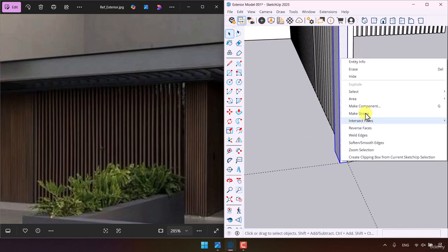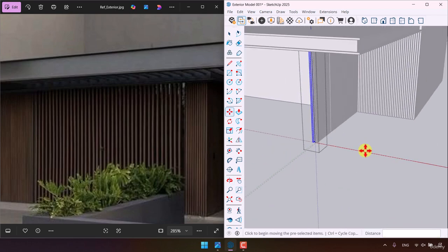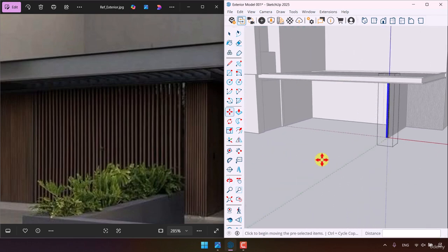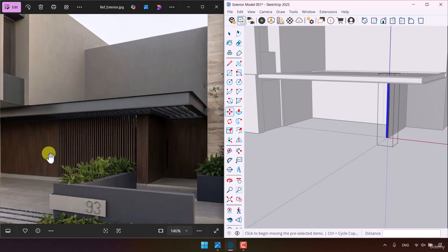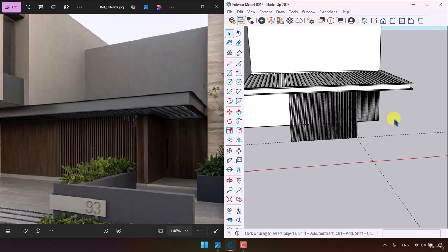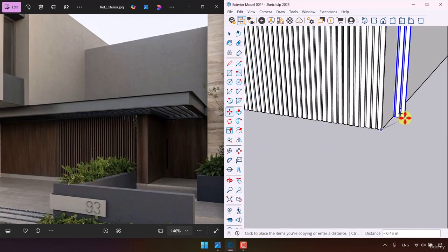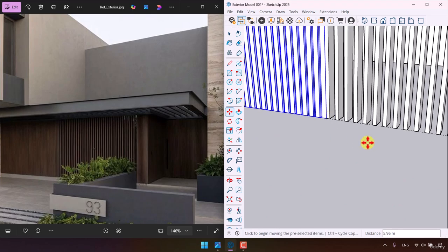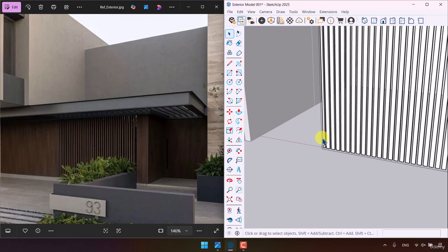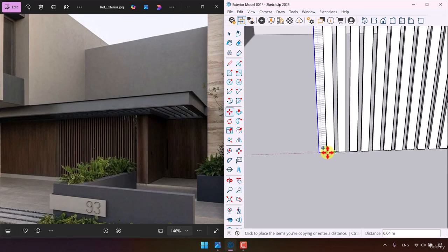So I'm going to click on it, make a group, Control A, and take my copies with some distance. So 0.08 is enough. And I'm going to repeat this copy about maybe 40x like this, and it's over. I can select the first panel which we created in here and take a copy to this area. And now I can continue my copying for finalizing my job.